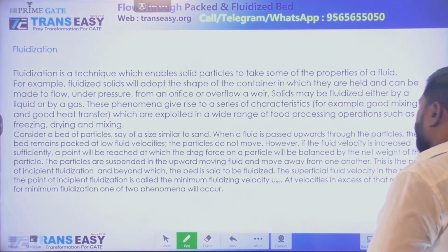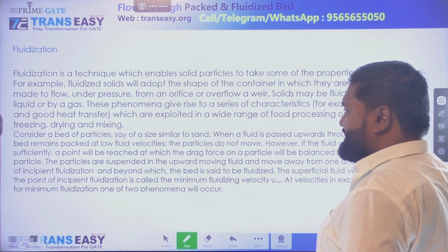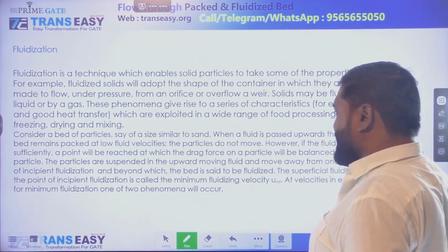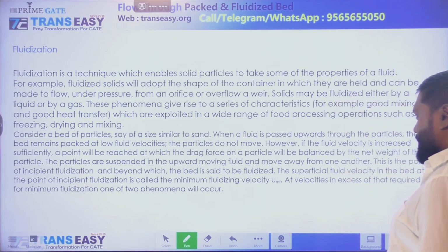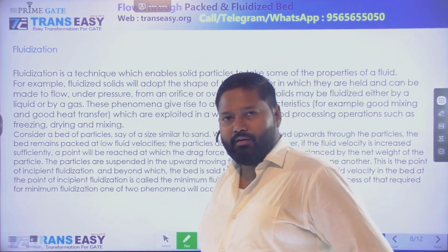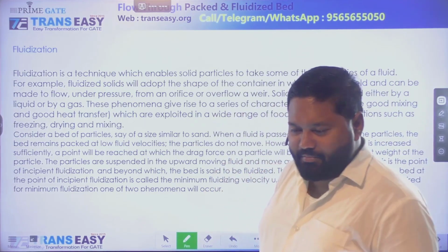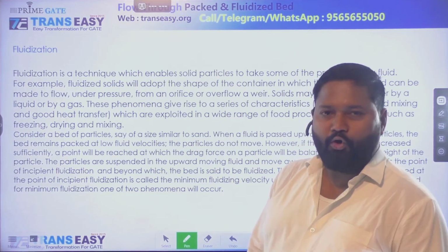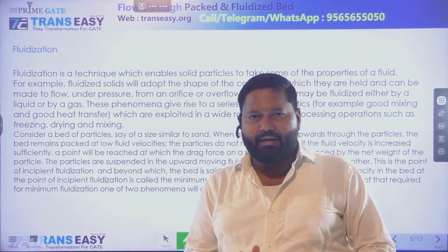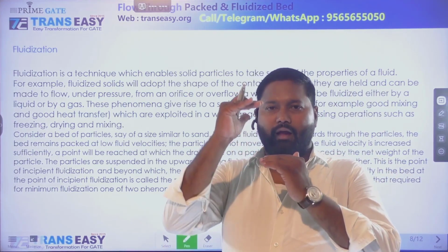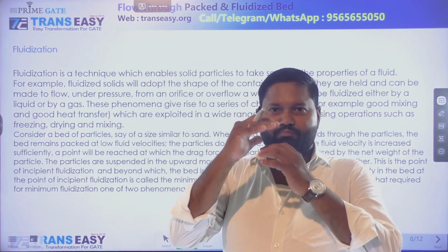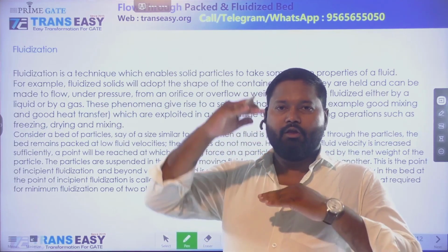However, if the fluid velocity is increased sufficiently, a point will be reached at which the drag force on the particle will be balanced by the net weight of the particle. So in that case, the particles will start moving in upward direction, they will expand, right?